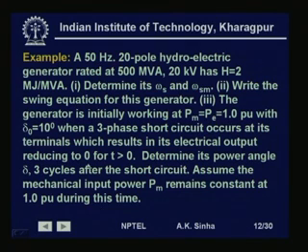Whereas, when at t is equal to 0 the fault occurs, the Pm remains same because the mechanical input to the generator changes much slowly, whereas the electrical output from the machine at t is equal to 0 plus has reduced to 0.